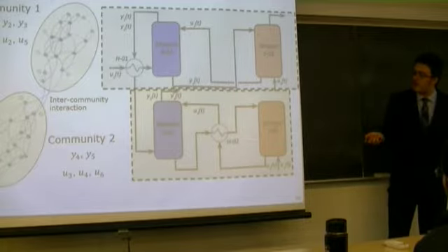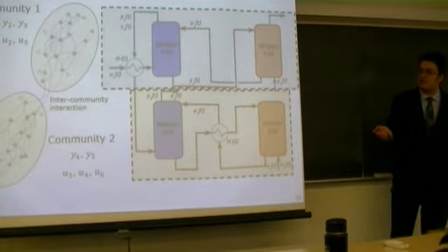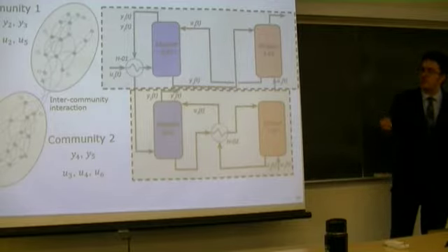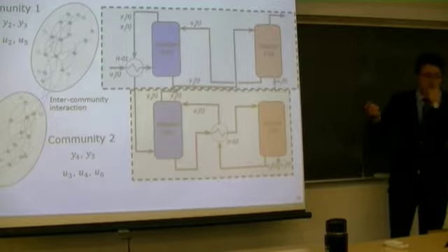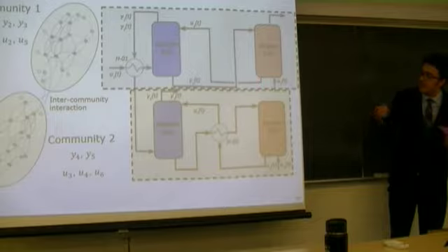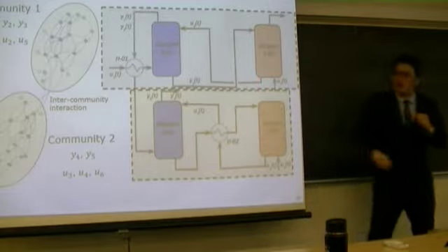Somebody may think that we may control each of those single units on its own, or we may only consider absorbers together for the control setting and also the strippers together. But the thing that dictates this type of decomposition is that the majority of the reactions are taking place in the amine streams.